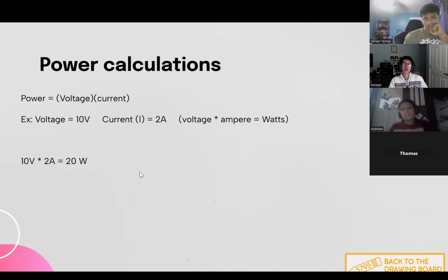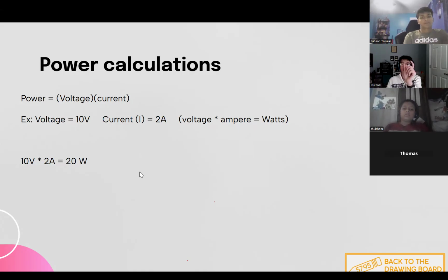The point of a fuse is to protect the circuit, and it works in the exact same way. When your circuit is pulling too much wattage, as you increase the amount of wattage pulled across a fuse, and they look like little glass vials, the amount of heat produced on that little fuse increases. Once it gets above a certain threshold, the fuse actually melts, cutting the circuit in half and saving your circuit from frying itself or setting fire in much the exact same way.